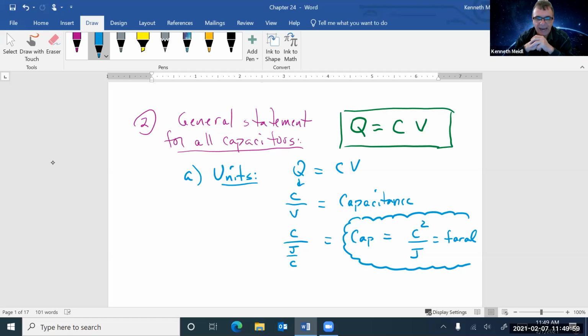And some capacitors can get expensive, but typically they're not. But I've got some that are about the size of a quarter in diameter, and they might cost you $50, $60, $70 because they're actually 1 farad capacitors, and those are giant capacitors. A lot of times a stereo system might need a capacitor like that in line because speakers have a difficult time pushing low notes.